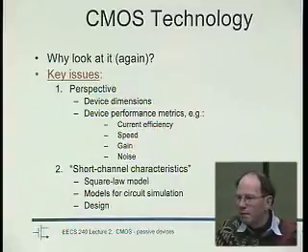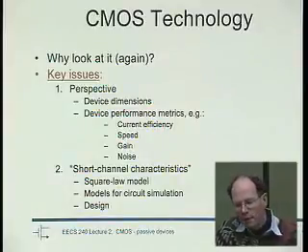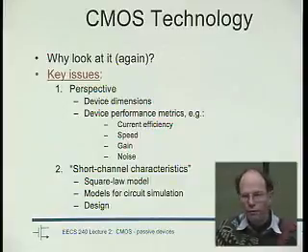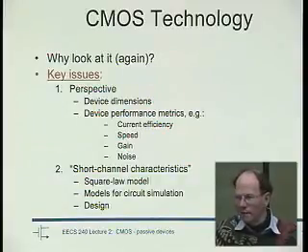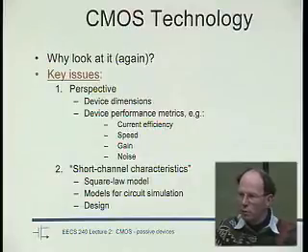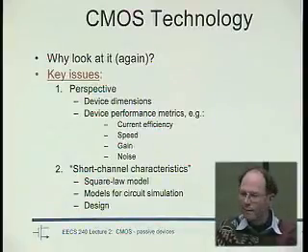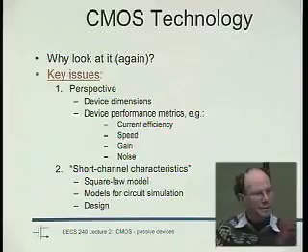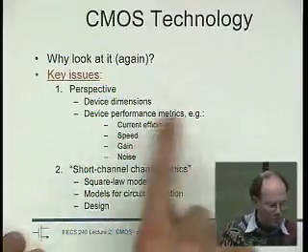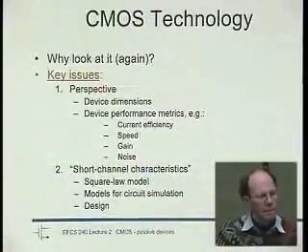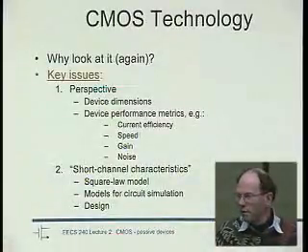That's also something that you, without doubt, have come across, right? In pretty much every device course, and certainly in every circuit course, they teach you first this wonderful model that usually is called the square model, right? ID equals 1/2 mu Cox W over L (VGS minus VTH) squared. So that's the square law model, right? Wonderful. Then you use that, and you somehow, in some foggy way usually, relate it to what you actually want to do, and you come up with a circuit.